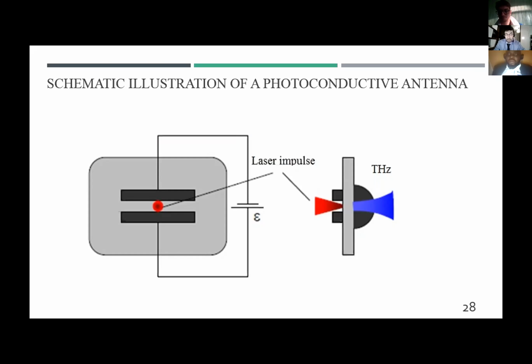For effective absorption of laser radiation with the release of charge carriers, the laser photon energy should exceed the band gap of the semiconductor, but sometimes multi-photon absorption is also used. The resulting free carriers are accelerated by the field applied to the gap, as a result of which there is a short-term current pulse, which is the source of terahertz radiation. Thus, an ultra-short laser pulse serves as an ultra-fast switch for the antenna, converting it from an insulating to a conductive state. The duration of the current pulse and the spectrum of the emitted terahertz wave is determined mainly by the carrier lifetime in the semiconductor.